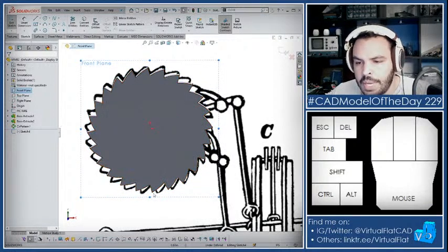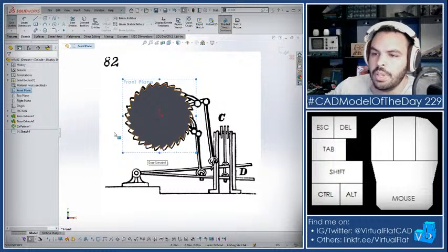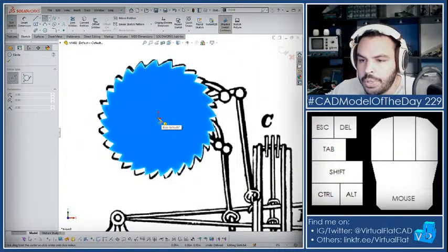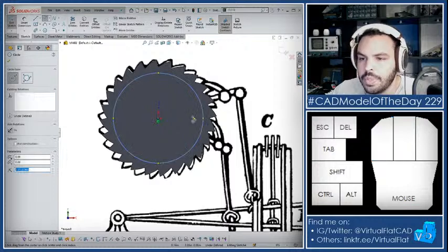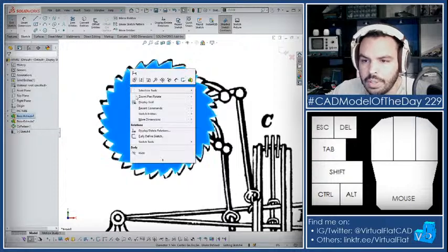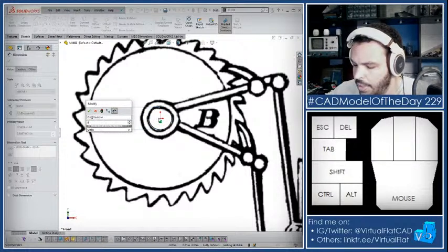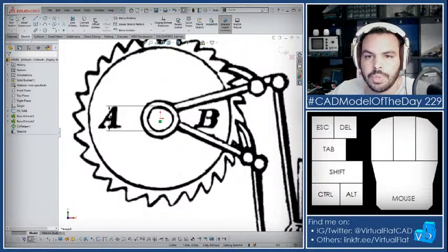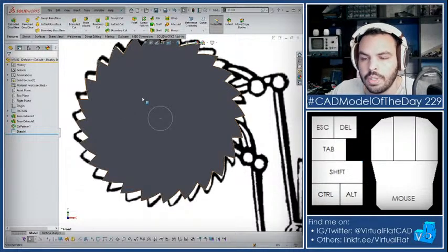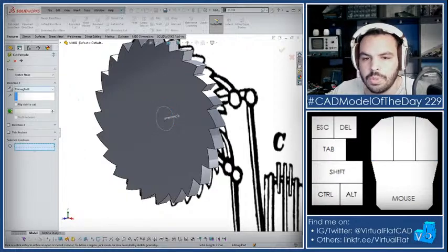Yeah, so you see it's not matching up with the sketch perfectly. That's fine. As long as it's a ratchet wheel, it should work just fine. Yeah, actually, let me get that inner hole. I can hide this body. Just kind of match that up with there and just give that 0.875 maybe. Looks pretty good. And I can just punch that through all. Why has it got contours? There we go.